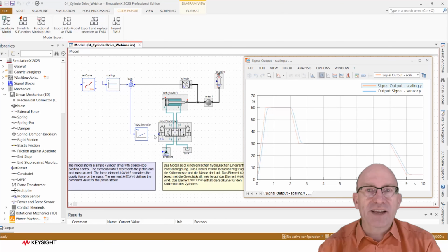In such a case, I would pick the physical plant, separate it from the controls which I use for testing inside my model. And then I just export this portion. And instead of removing the unneeded portion from the model for export, I now can export a submodel, which makes it much more convenient, and I re-import the FMU here. I also can do some testing. I can see if it works properly. I can see if it connects to my simple control here properly before I deliver it to my partner engineer who is building the controls.